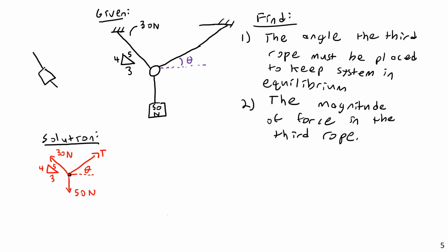When I have slopes like this, a system of slopes, I usually don't actually go and find the sine. In case you're not familiar with this, statics is often the first time students see this method. If you already have the slopes of your force, if you already know the direction of it via slopes, you don't need to actually go and calculate the angle. In fact, that makes it unnecessarily complex and just introduces more chance for error.